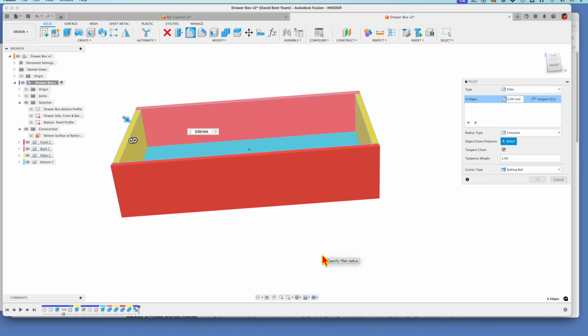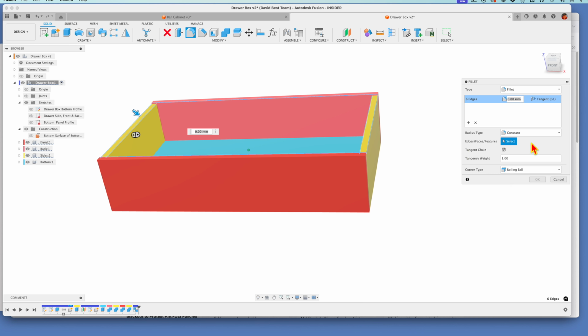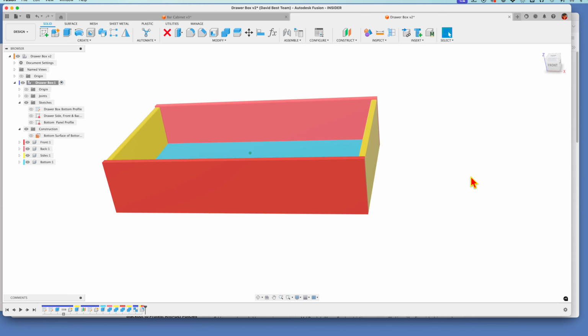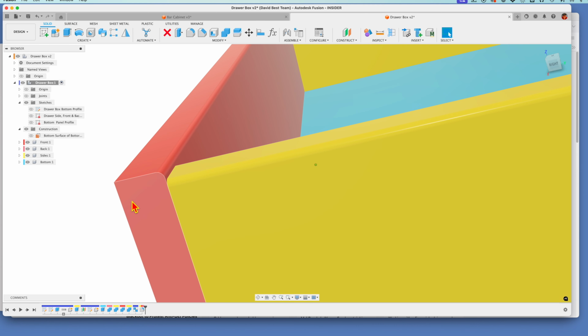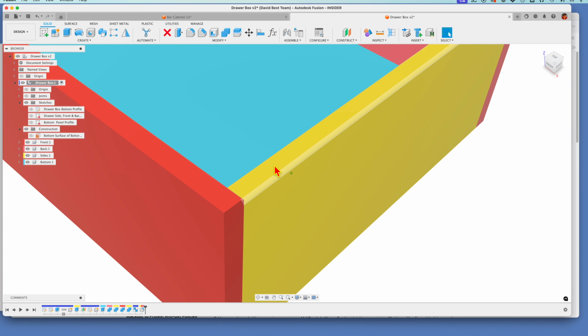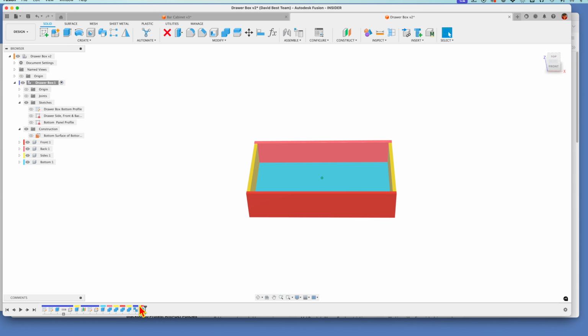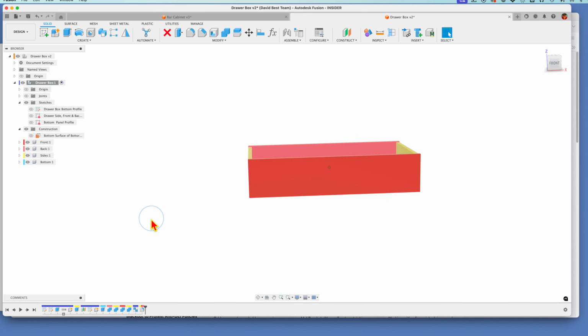And the amount of fillet that he uses is 3/32 of an inch. So let's see if we can specify that here, 3/32 inch. Does that get us something? Let's see. Yeah, we got a nice eased edge all the way around on those points. And we've got a feature in the timeline here. If we wanted to edit that and make it something different, we could do that.